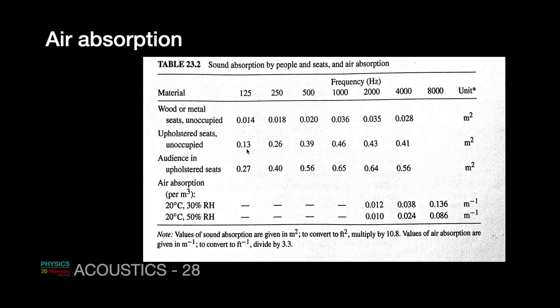Therefore, in an old-styled theater where all the seats are, say, wooden, you cannot simply remove the wooden seats and bring in cushioned seats, because the reverberation time will change, and sound production will change. You will have to do something else to balance it.